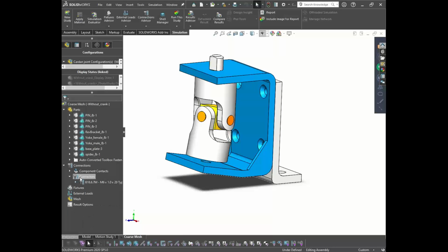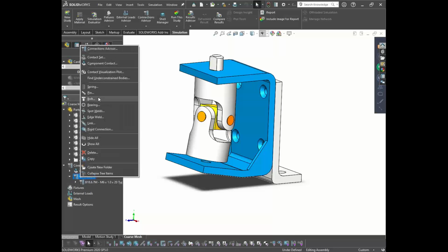Okay, so there are different types of connectors like this. This one was the bolt connector. There's a spring connector also. So the purpose of connectors is you need not model the CAD model on your part. You simply consider the properties of it so that your meshing time will be reduced very drastically. Sorry for that. Okay, so there's one more connector, that is the pin connector.